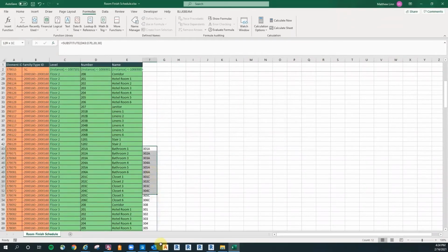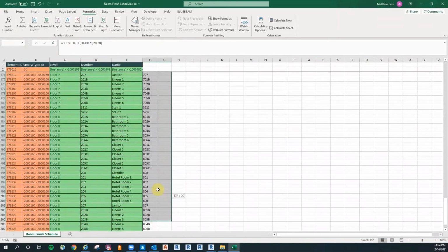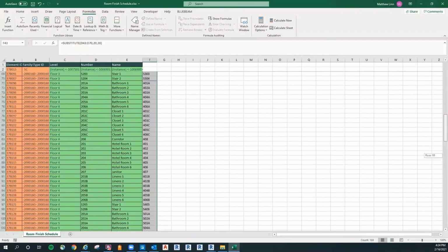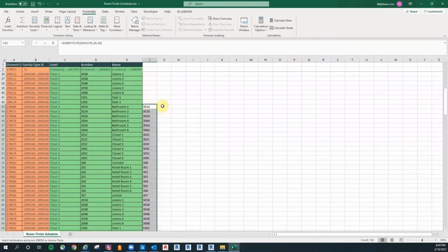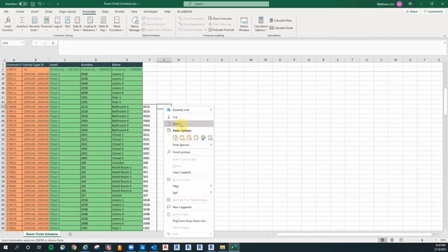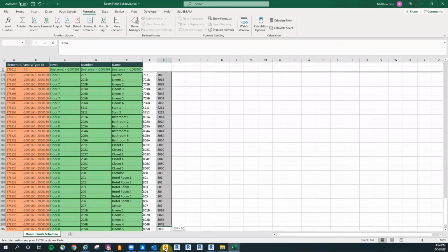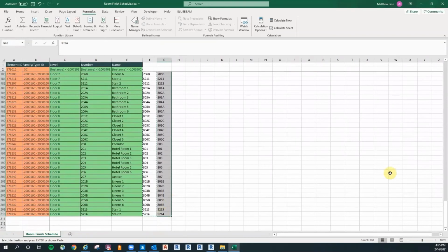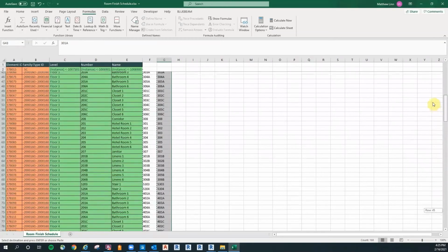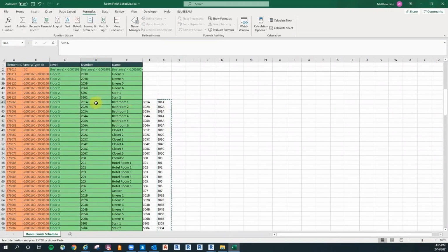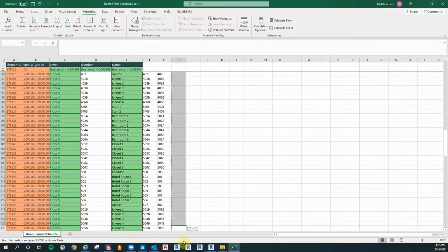Okay, just like we did previously, any numbers that are being driven by a formula, you don't want to copy the formula. You want to copy the value. So I'm going to come back in and select all of these, copy to clipboard, paste special, okay, and then paste values. Okay, these are the ones we want. Those are just the values, no formula attached. And I'll copy these back into the room number cell value, paste, okay. Get rid of all this stuff I did in the margin. I don't need it anymore.